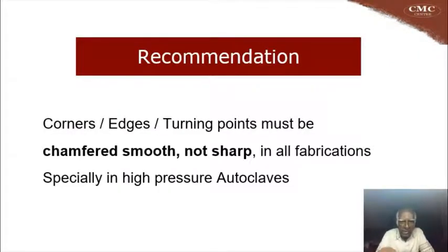So the recommendation to prevent this failure: the corners, edges, and turning points in any fabrication of any vessel must be chamfered smooth and not sharp in all fabrications. And this is particularly important in high pressure autoclaves because autoclaves work under high pressure and these sharp corners will initiate corrosion and lead to leakage.